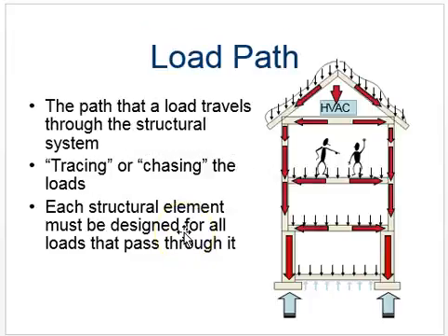Load paths. This is really important. This is what we're going to be working on. A lot of our loads come here on the roof, but we also have loads on each one of our floors, and you can see it by the little arrows going down. And what happens is these loads travel down until they reach the ground, until they reach the footing.